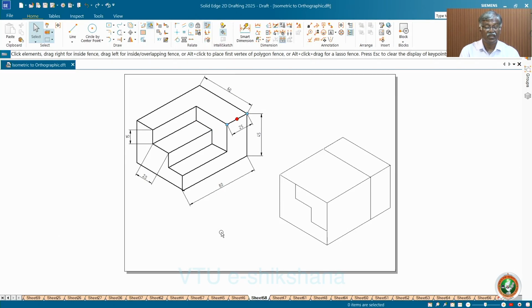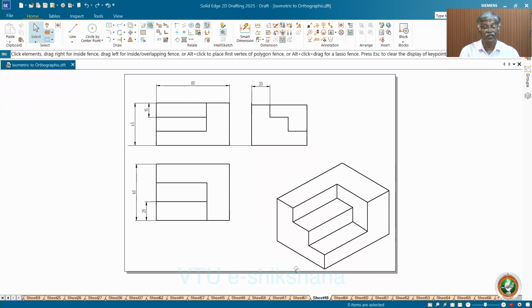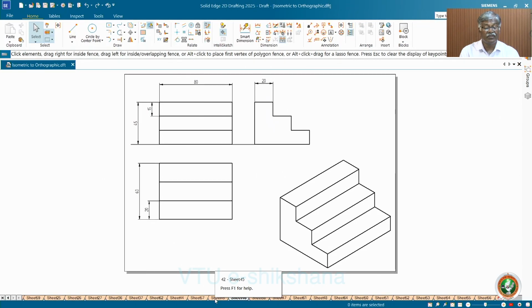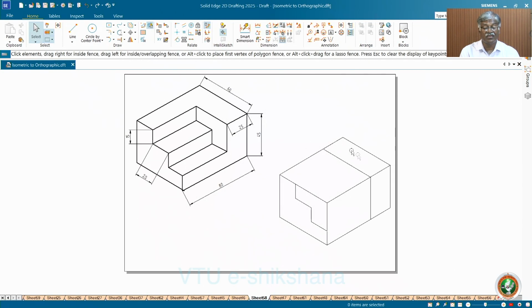How to do it? Here are the top and front views. For that they give it like this. These two they give. So to create this, you take this front surface box you create and leave 25 mm as per the given dimensions. Draw one more line. Instead of shifting the entire profile till the end, you rotate, you fix this to move to this point only. Now you get this one.